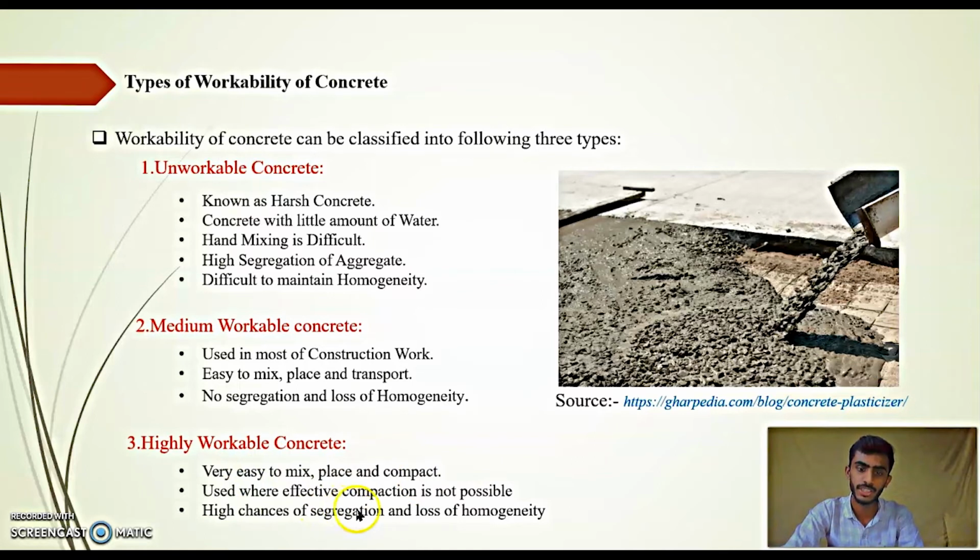There are high chances of segregation and loss of homogeneity. Due to highly workable concrete, the water ratio in the concrete is more. Therefore, there are chances of segregation. After placing the concrete, the water will remain up and the coarse aggregates will go to the bottom. Therefore, it can also cause honeycombing.